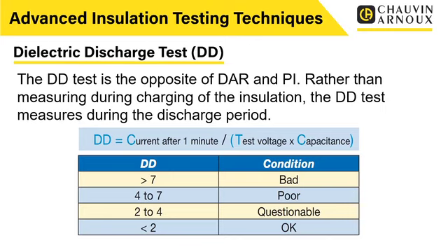So there are applications where this would be better than others. And as I've said before, sometimes people will apply all of the tests, or a couple of the tests together, just to collate the insulation readings, to make sure they're all giving a good reading, rather than a lower reading on one where you're getting good readings on others. That might indicate something that you need to investigate further, shall we say.